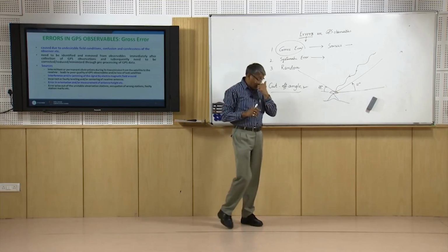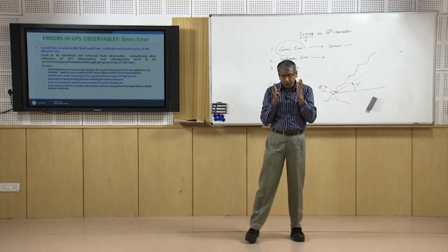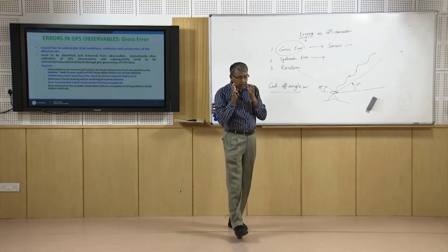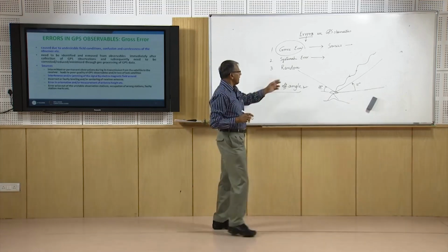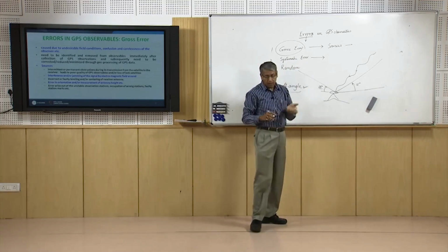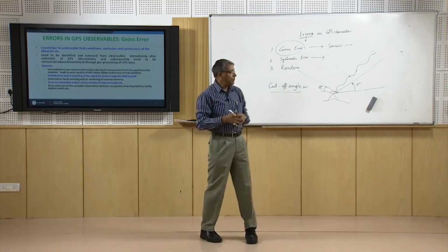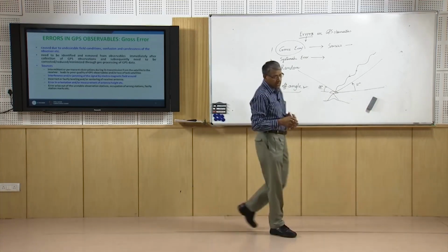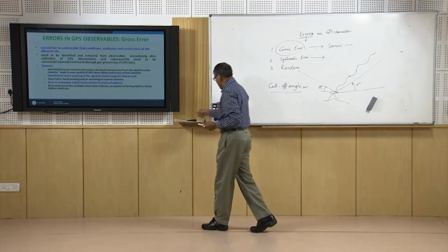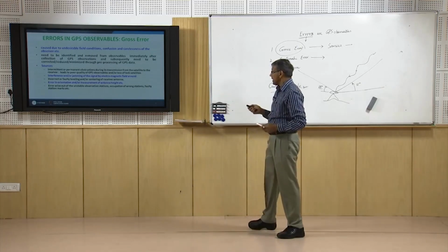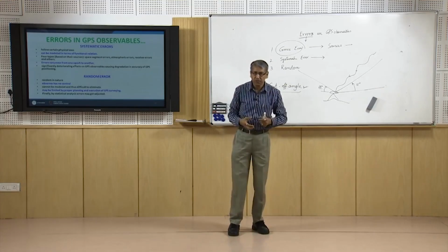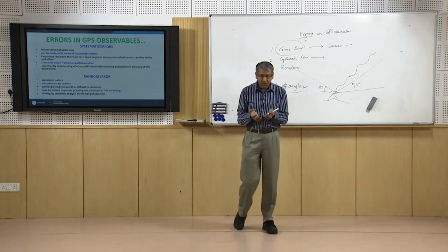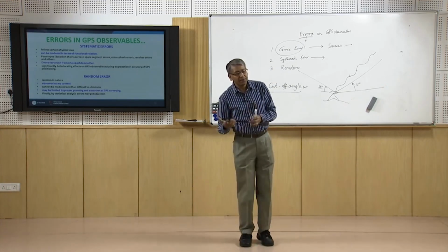This is specific to the instrument or procedure. In GPS there may be different types of systematic errors present in the observation. They may arise out of the satellite space segment, during transmission through the atmosphere, from the receiver, or in some other way.